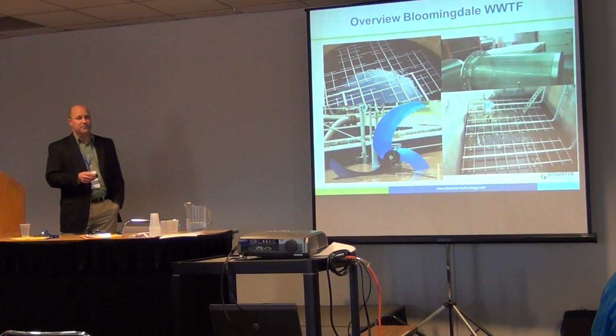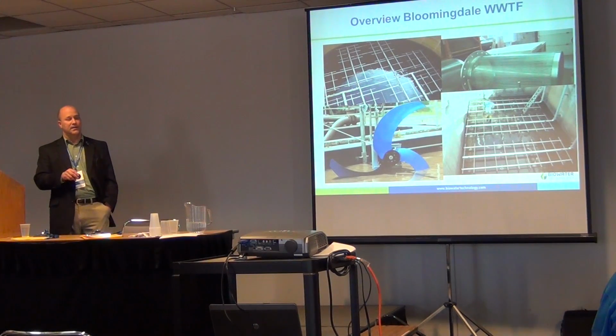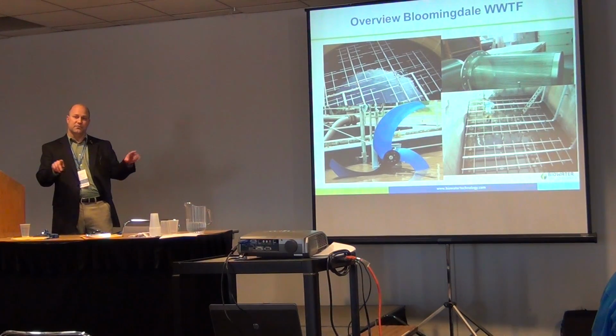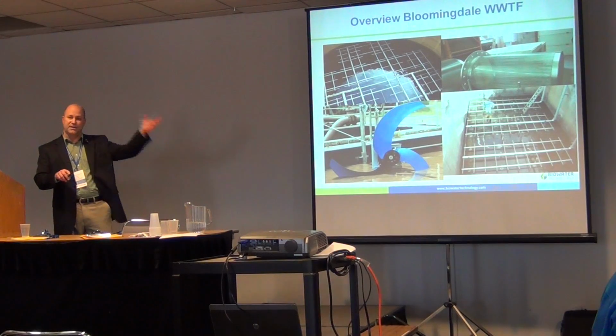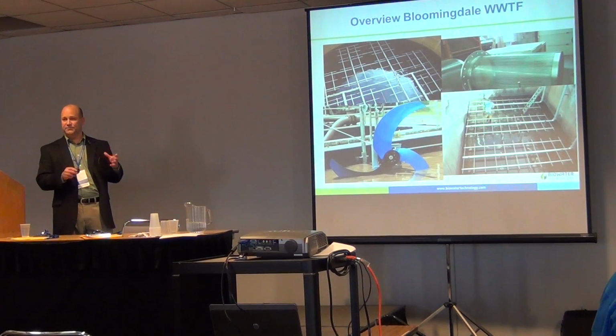The other critical design in maintaining a fixed film system for BOD reduction and nitrification is the aeration grids. And I have two depictions here. One is in a circular tank and one is in a rectangular tank. And you'll notice in both of them that they both have full floor coverage of aeration grids. You want to have the bubbles moving up and around the tank so that media is being mixed all throughout the tank. It's critical that the media and the substrates come in contact with each other.